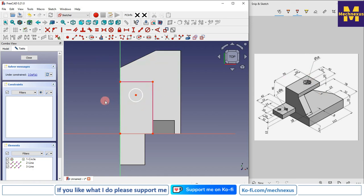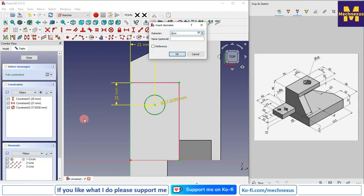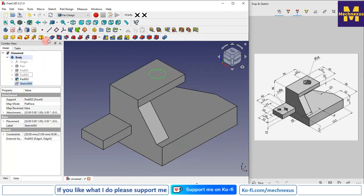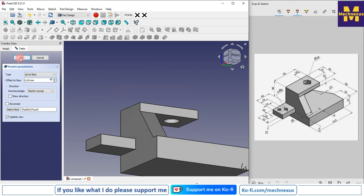So create a circle, and this point to this point give the 20 mm, and this to this is a 21, and hole diameter is 18, so give the 18 mm, and now click on close. Now click on the pocket tool and select up to face and select this bottom face, click on OK.